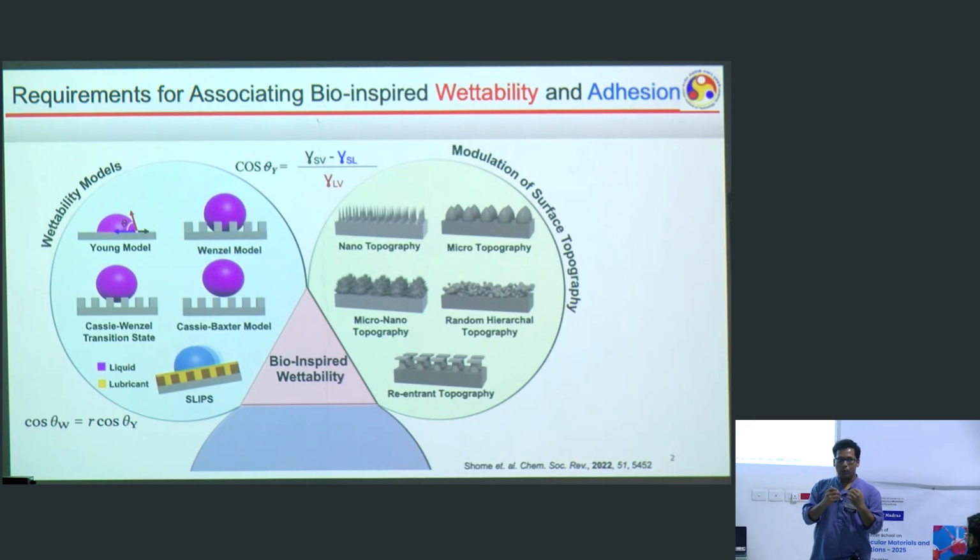Okay, this wettability cannot be explained based on Young and Wenzel. You cannot really find any roughness factor that explains this, because it crosses this cosine limit. This roughness factor will always be more than 1, right? So it's not theoretically possible to explain a contact angle as high as above 150 degrees with Wenzel, and forget about the Young angle.